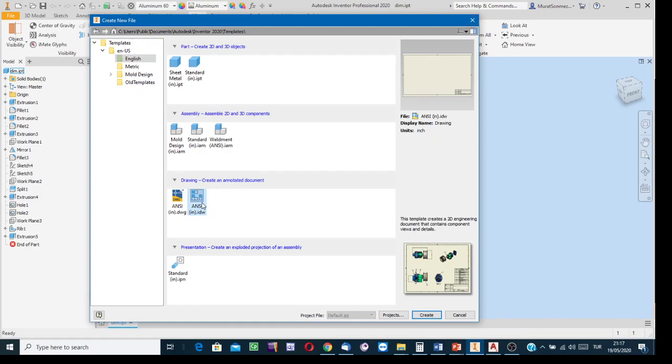Of course, at this stage, I'm going to answer the question. Although you created the model inputting the values in inch, how you can show the dimensions in feet? Foot is the unit of measurement widely used in civil engineering in architectural drawings. Not inch, but foot.